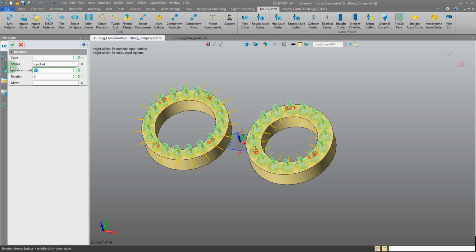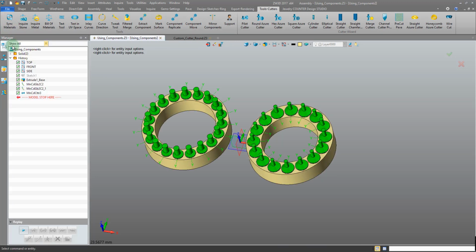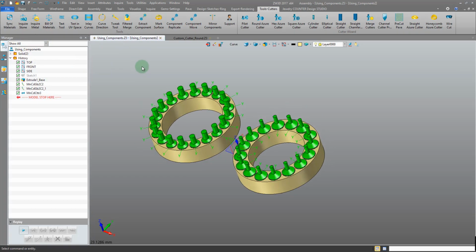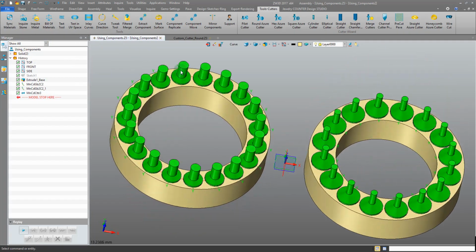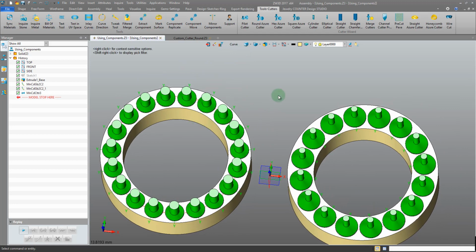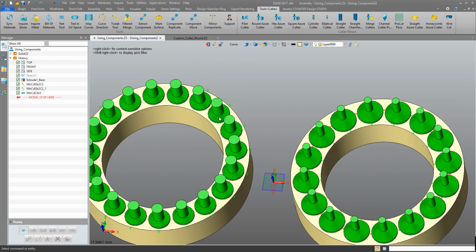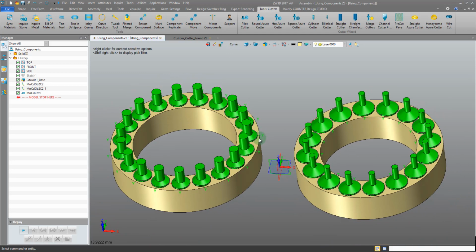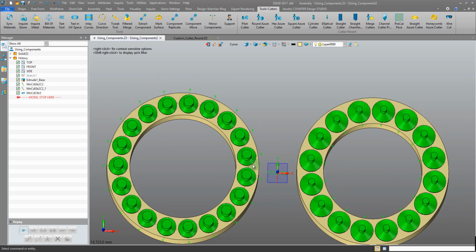And let's give it a 0 elevation. And other than that, we'll just use the default parameters and kind of cancel out the tweak. Okay, so we have our cutters, and they're placed on two different sizes of gemstones. I believe there's 1.25 and 1.5. And our cutters adapted to match the diameter of the stone.